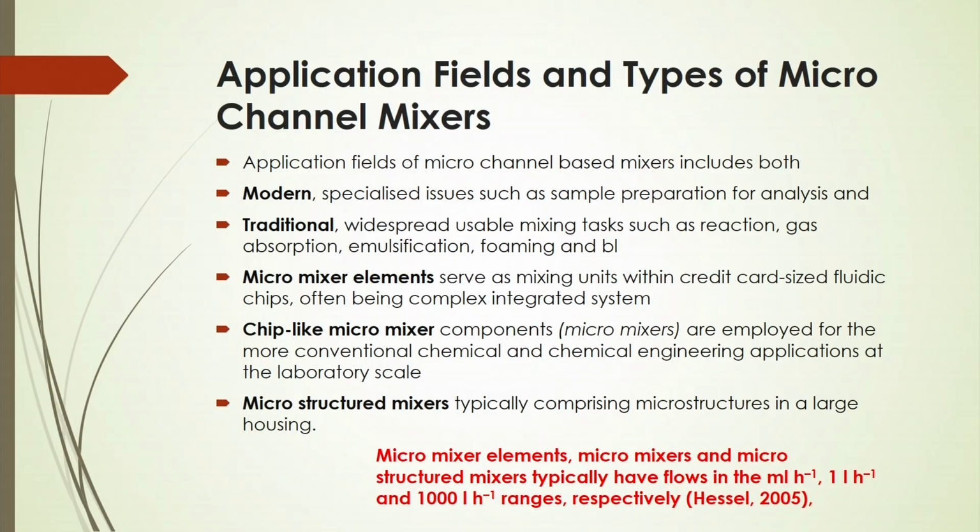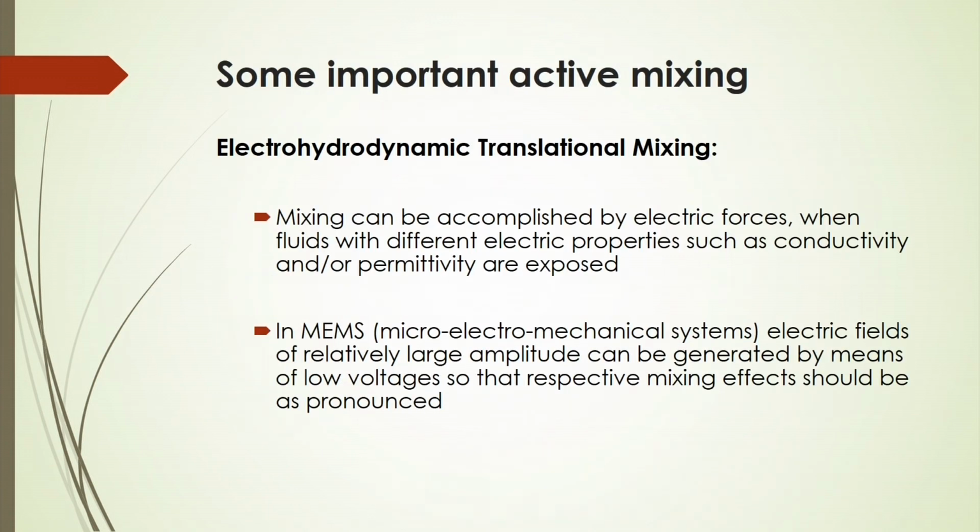So, in that case we can have these different applications within a certain range of micromixing efficiency based on the channel structure. Some important active mixing, like electrohydrodynamic translational mixing, can be accomplished by electric forces when fluids with different electric properties, such as conductivity and permittivity, are exposed.